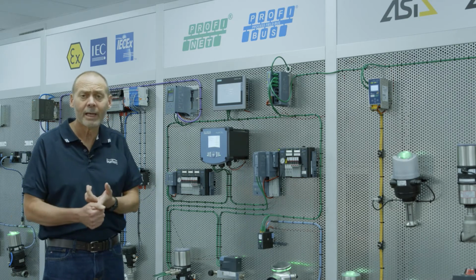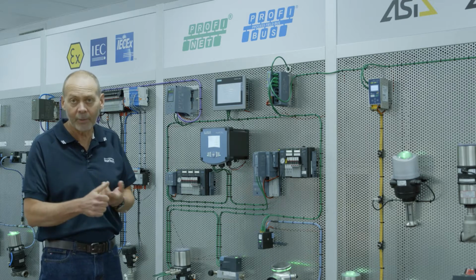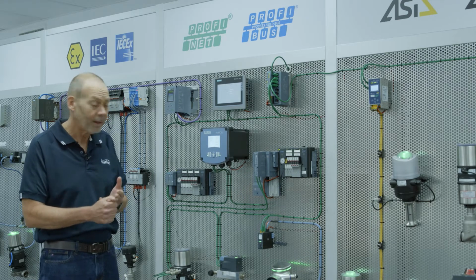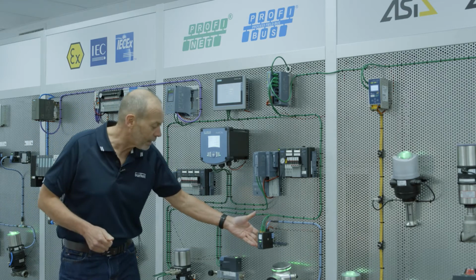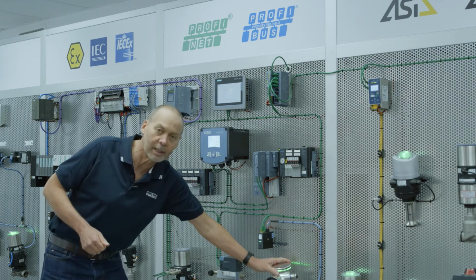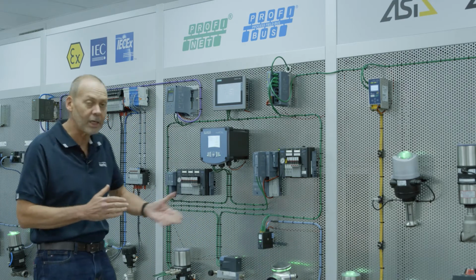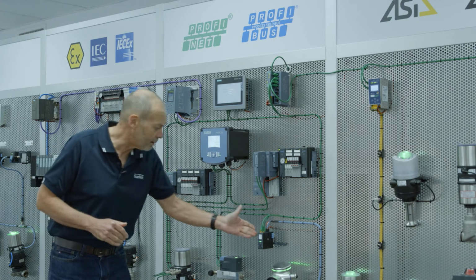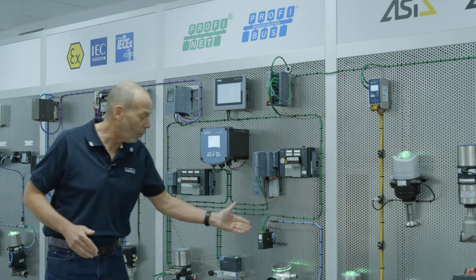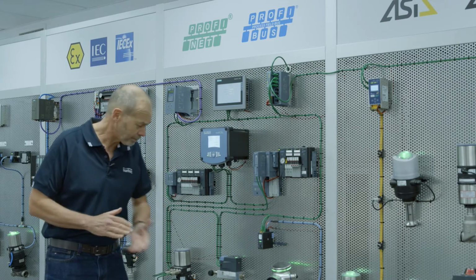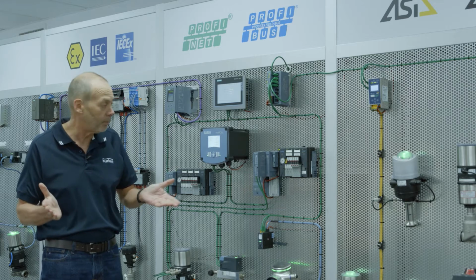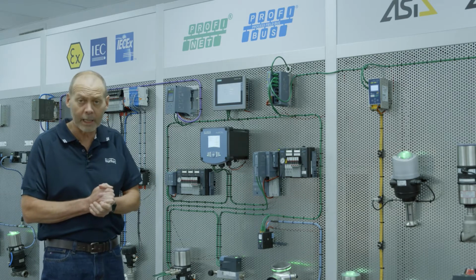The third way, of course, is when we connect via a gateway to a sub-network, and this sub-network could be the Bürkert EDIP network, it could be IO-Link, or it could be ASi. In this instance, we're showcasing that by connecting to the Bürkert ME43 and then breaking into the EDIP network, where we're showcasing one of our hygienic flow meters. From that sub-network, you could put a cluster of valves, maybe 60 valves if you like, all on one PROFINET node. All of these connected devices are capable of being part of that MRP, or redundant ring protocol.